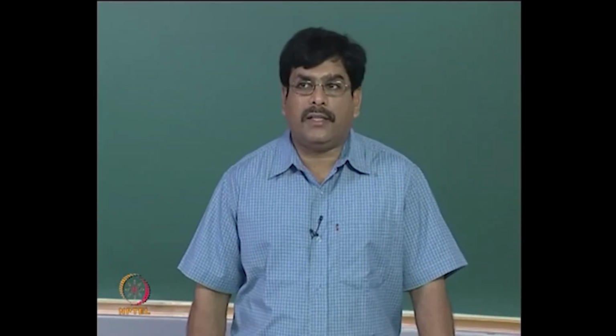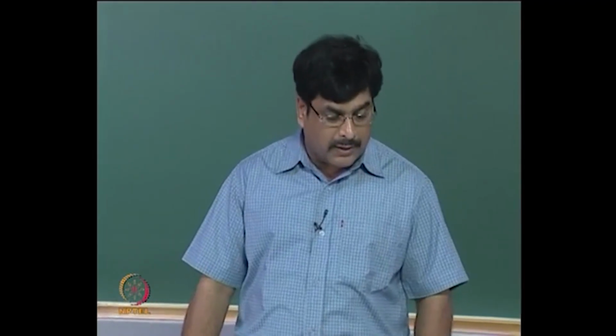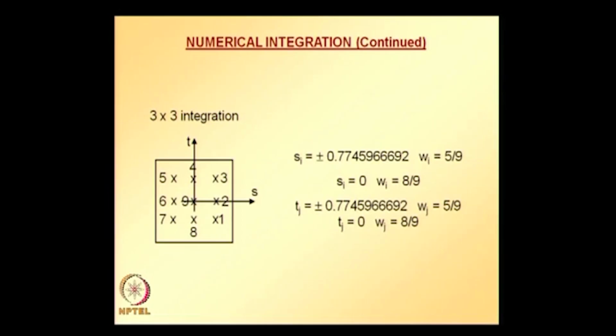Calculating the weights as I explained, weight in the s direction times weight in the t direction, we get weights at all the points, and also by combining the coordinates in the s direction and t direction, we can get the coordinates of all points for this 2 dimensional integration. So, a similar procedure can be extended for any order of integration.